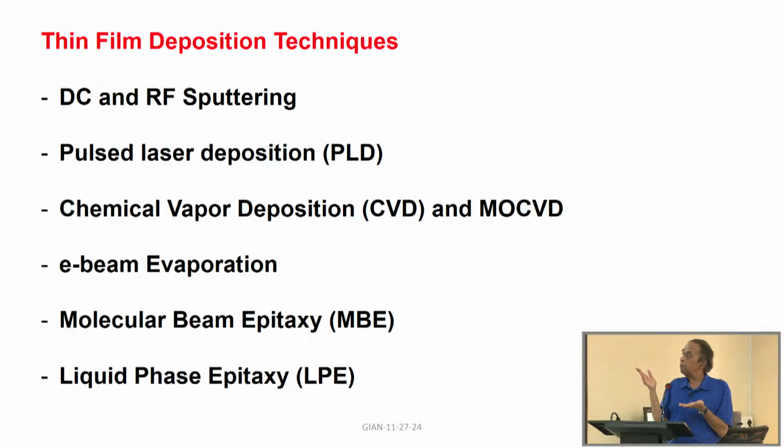So, there is always a substrate on which the films are deposited. In chemical vapor deposition, you have a gas carrying the metal ions or anything that you want, and there is a substrate which is heated to maybe 400 to 600 degrees. When the gas flows on top of the substrate, the film will be deposited onto it. So, it is chemical vapor deposition or metallo-organic MOCVD, based on a similar principle.